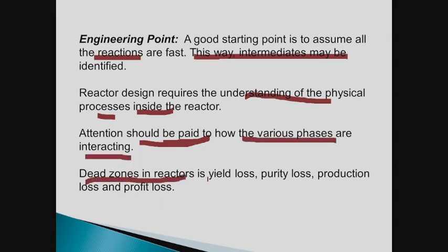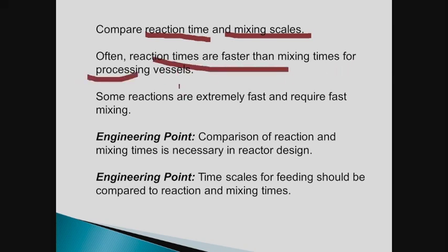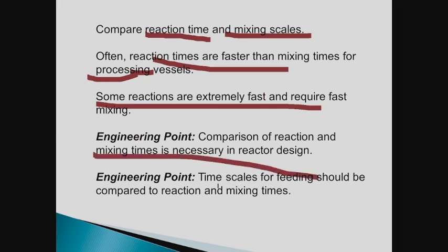Dead zones in reactors mean yield loss, purity loss, production loss, but the biggie for the business people is profit loss. And of course, as I said earlier, you have to compare reaction time with mixing time. Reaction time is faster than mixing for most processing vessels. Some reactions are extremely fast and require fast mixing. Comparison of reaction and mixing times is necessary.